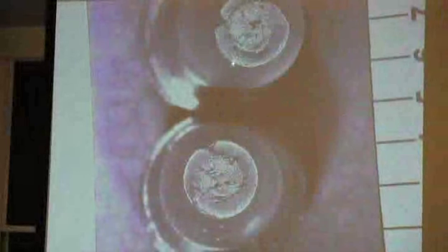This is the ends of the cup cone fracture, and this is the cup, and you have a 45-degree shear. This is what we call plane stress, and I think Dr. Belmar has talked about plane stress, and he's probably talked about this region in here is plane strain, and this is the cone, this is the cup. That's nice. How about this?